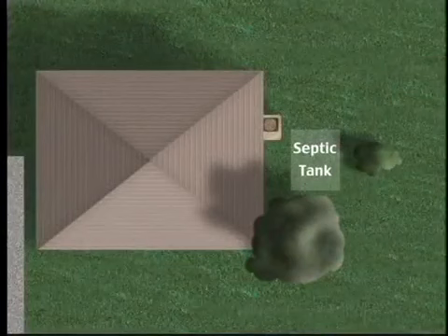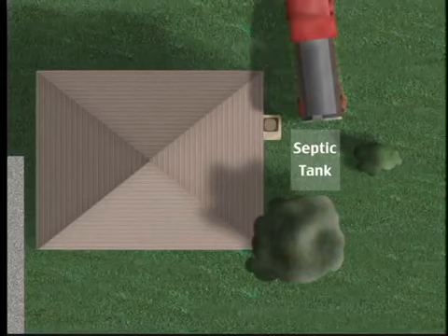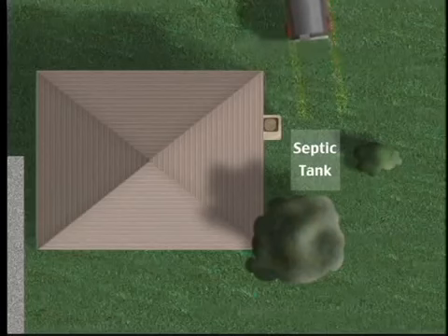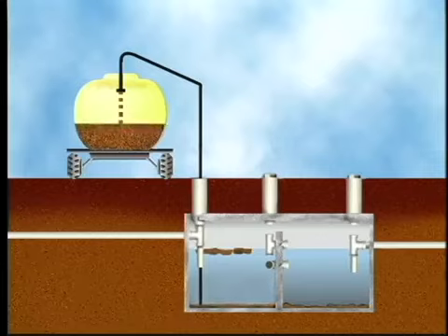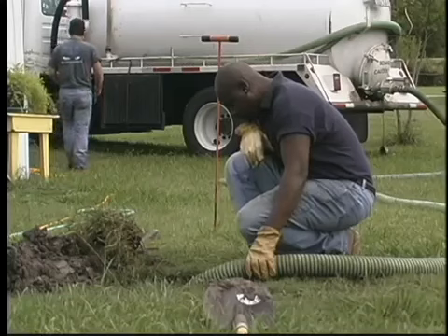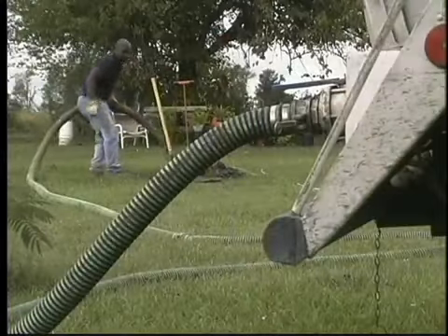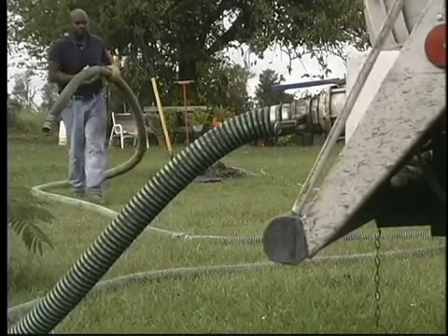The location of the treatment system is critical. Though a treatment system must be a minimum of 5 feet from the building, it is usually placed further away to allow better access for operation and maintenance. Periodically, you will need to have solids pumped from the treatment tank. This is accomplished by a vacuum truck with a hose that extends down into the treatment tanks. Pre-planning on how this truck will be able to get to the tanks will assist further maintenance.